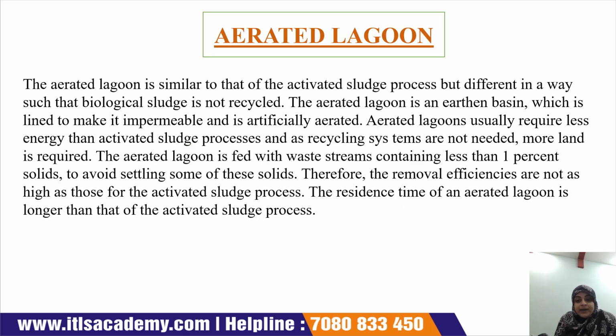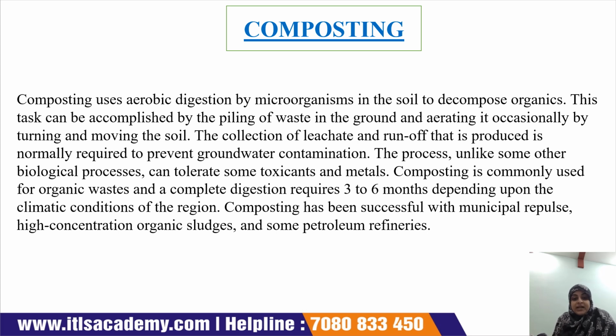The next method is the aerated lagoon. This method is very similar to the activated sludge process, but differs in that the biological sludge is not recycled, and the aerated lagoon is an earthen basin which is lined to make it impermeable and artificially aerated. Now the next treatment is composting, which is aerobic digestion by microorganisms in soil so that they decompose the organic material. This can be accomplished by piling the waste on the ground and aerating it occasionally by turning and moving the soil.